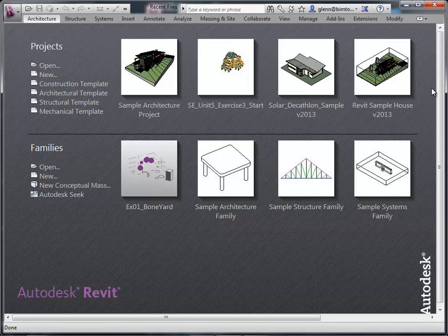And then when it was time to actually work with it, they would all use this as the base reference. It's the design record, and ultimately it's the construction docs too. We do it all through a 3D model. One really good thing about 3D modeling is that in having to construct a 3D model, even at a funny scale, we actually have to resolve a lot of issues that would ultimately come up in the building process: how that connection is going to work, how the joinery is going to work. You really have to understand it when you go with a 3D model. You have to get to how it's going to physically be built.